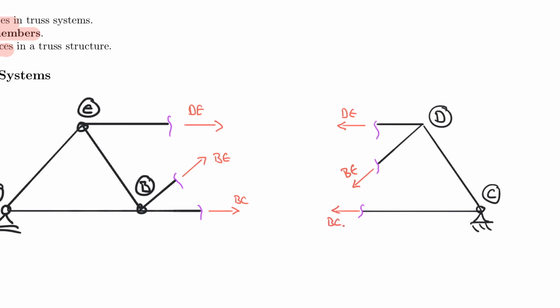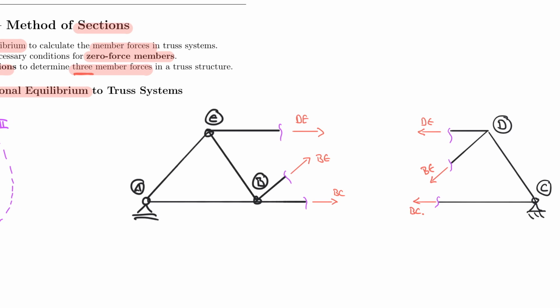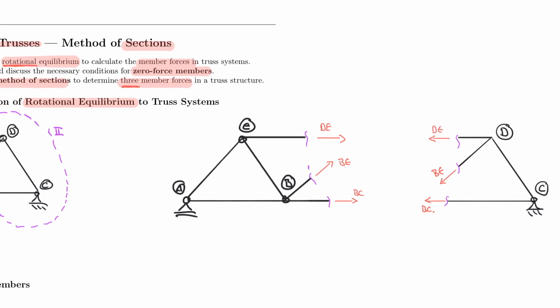And so now we probably already understand that we can separate these structures and we can cut, because remember that in mechanics the cut always works as long as you bring the forces back in that you released. And now we have to find out how we can generate equilibrium for each of these cuts, because remember, equilibrium must pretty much exist for this system here just as it has to exist for the other side system.